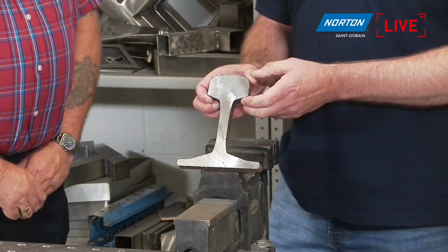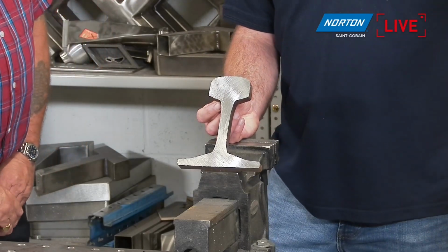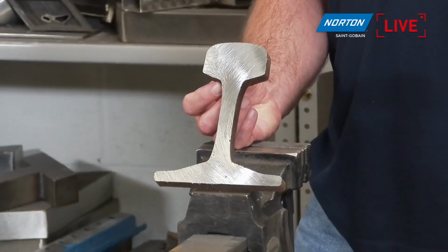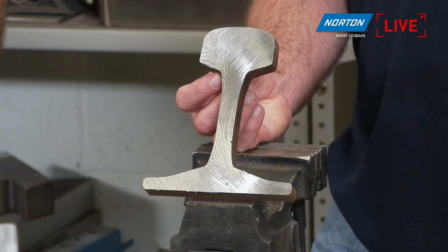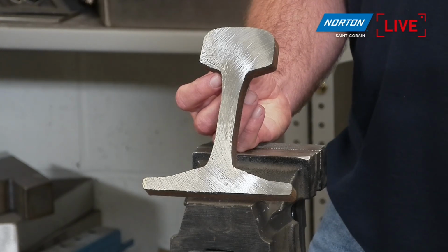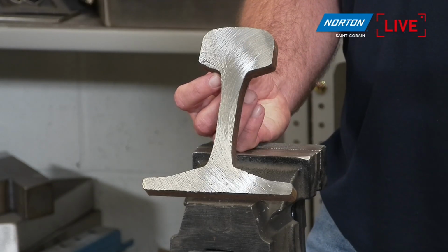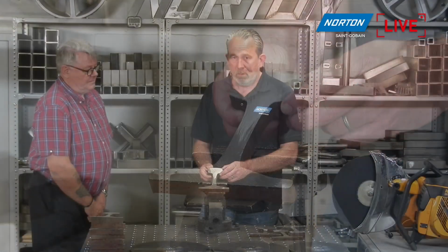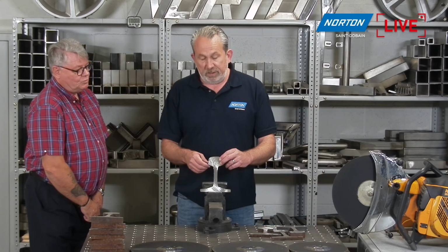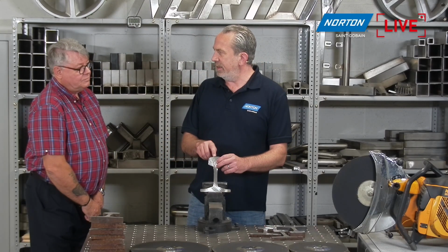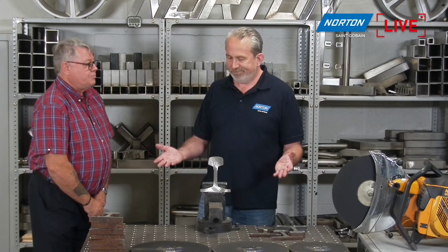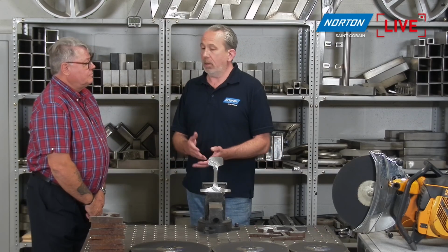And here we have in front of us a section of the UIC 60. What does 54 or 60 stand for? It is the actual weight per metre of rail. So it's 54 kilograms per metre and 60 kilograms per metre. So this is the one that's 60 kilos per metre of rail. Okay, no problem. So that's the different types. And you say UIC 60 is for the busier lines, high wear areas where there's more traffic. It makes sense. It's going to last longer, so you can keep that track running for longer using the heavier duty rail, essentially. Absolutely that.